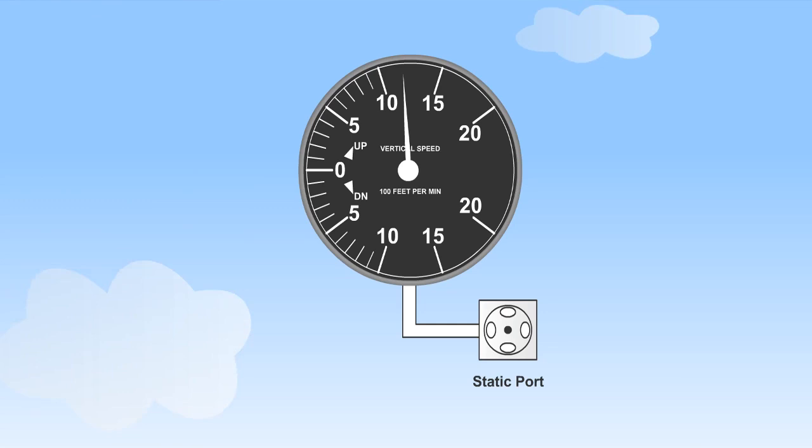Instrument, position, maneuver-induced, and time lag errors are all to be expected in a normally functioning VSI. When considering the VSI, however, a blockage or leak constitutes a malfunction and should be viewed as such. A blockage in the static source will result in the VSI ceasing to function.